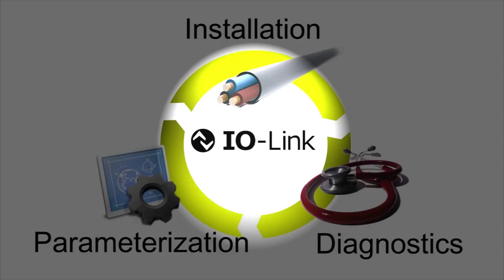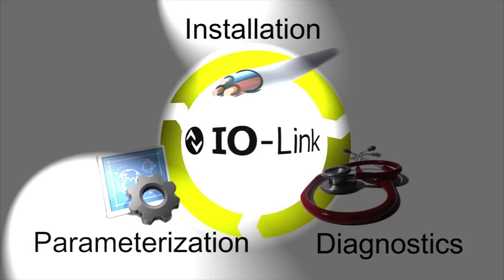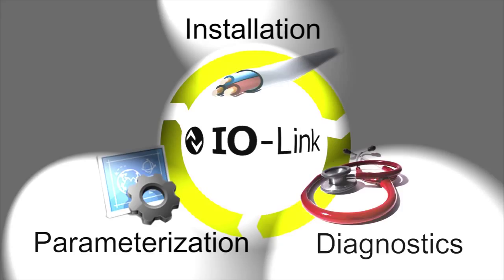What benefits does IO-Link have to offer? There are three main benefits: installation, parameterization, diagnostics. An IO-Link solution just requires one type of connecting cable, a standard non-shielded three-wire cord set. Sensors and actuators are smart, meaning they usually possess microprocessors for parameterization and internal data processing.